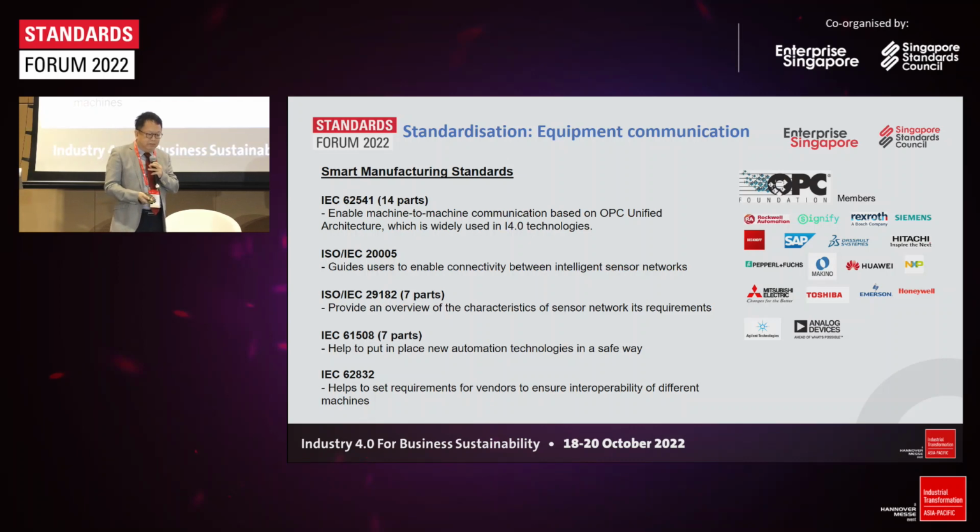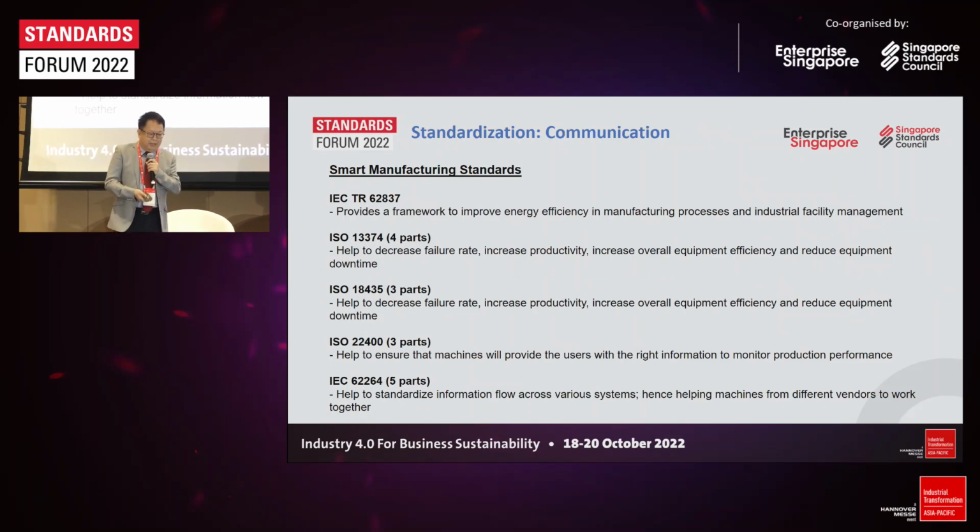I will use one example, OPC UA. OPC UA is one of the popular standards being used now. So what is OPC UA? In the past, when we did digitalization, we only needed data transfer, MTConnect or whatever, or you have an IoT with a gateway and you only transfer data. But now, going into advanced manufacturing, you require command and control in real time. So command and control must have a standard.